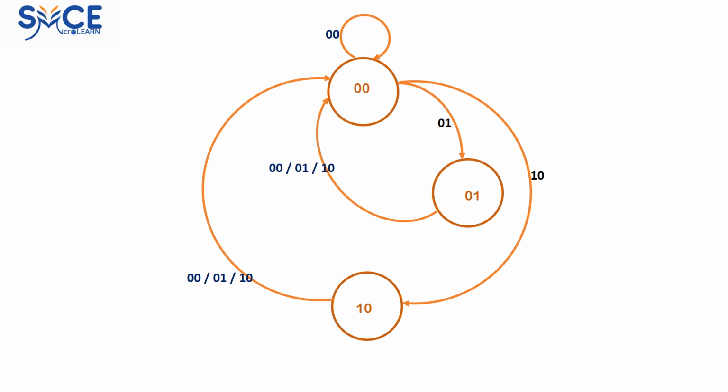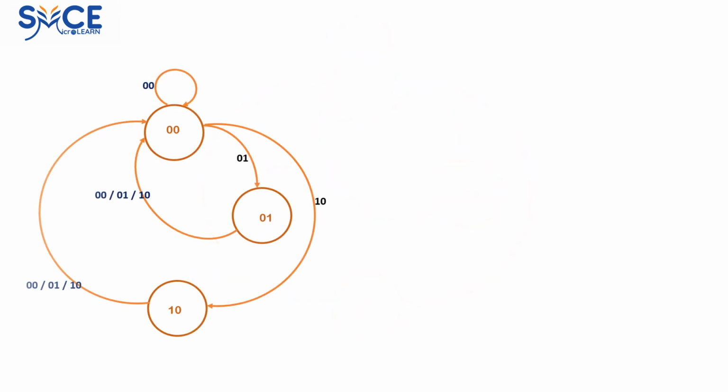We are now ready with the final state diagram, and let's go ahead to implement it as a hardware circuit that will act as a controller for the toy vending machine. You must have observed that when the inputs and outputs in the decimal were converted into binary format, they became a binary number with a 2-bit representation. Thus, the inputs and outputs with a decimal value of 0, 1 and 2 get transformed into a 2-bit binary equivalent of 00, 01 and 10 respectively.